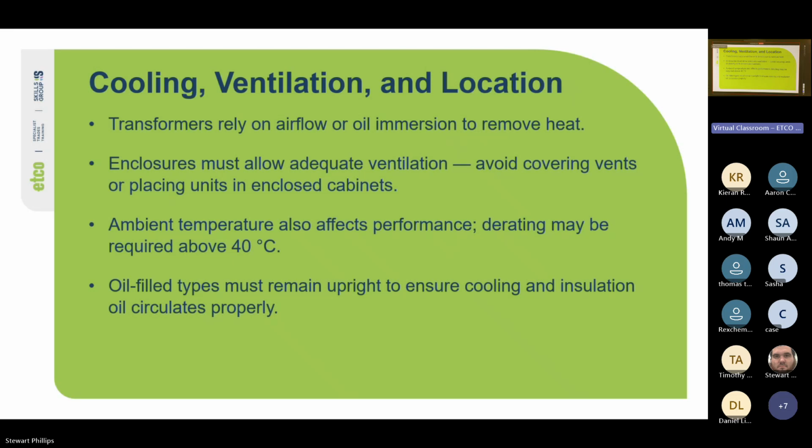Yeah, so ambient temperature. This is a big thing. Obviously, with climate change, the ambient temperatures are changing quite a bit. So in summer, it's getting quite hot in certain parts of the country. If you're in the sun, it gets really hot. And because it's so hot, we're still running our air conditioning units. So that can affect the transformer's performance. And this will degrade the transformer over time, thus leading to more transformer issues.